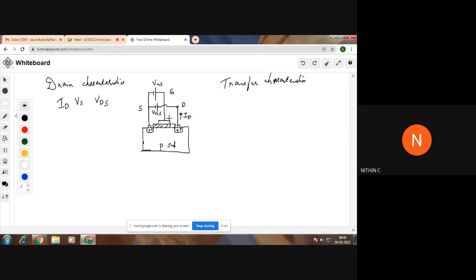That is the voltage VGS that we apply to the gate or metal. This is the metal, this is the oxide layer, and this is the semiconductor. That's why we call it MOS. So the gate-source voltage VGS that we apply here should be greater than the threshold voltage. Then only what happens? An inversion layer, or a layer of electrons, will be formed over here.